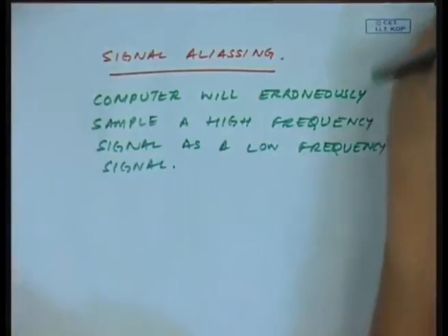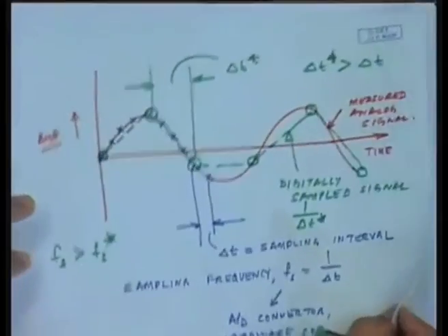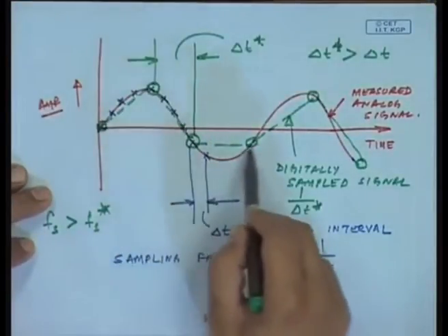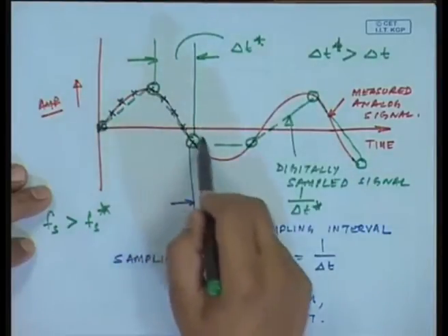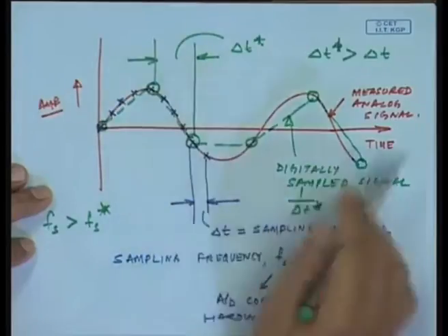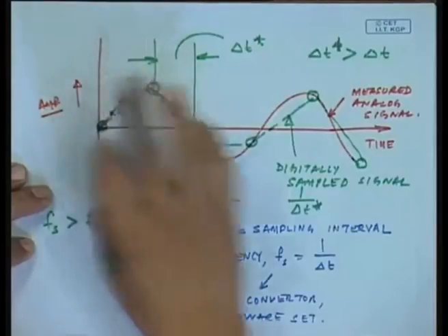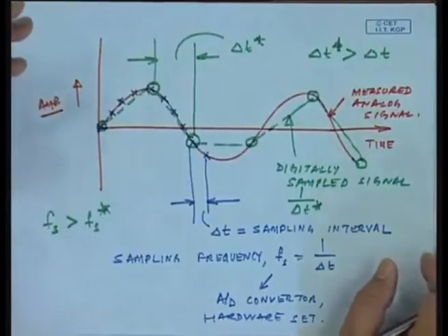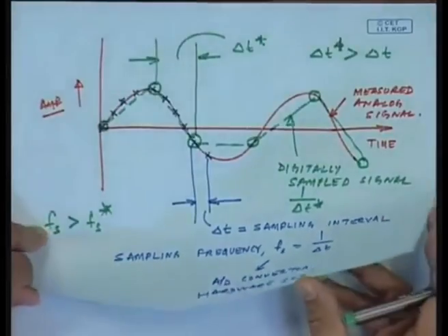Okay. I will go back to the previous example or the figure which I had drawn. If you look here, the original yellow red signal will be misunderstood as a low frequency signal if your sampling is not adequate, and then the FFT will have a lot of low frequency peaks in the frequency domain. So, this has to be avoided. I mean, we will be thinking that the sampling frequency, whatever the computer has obtained by its sampling, is correct, but that cannot be true.